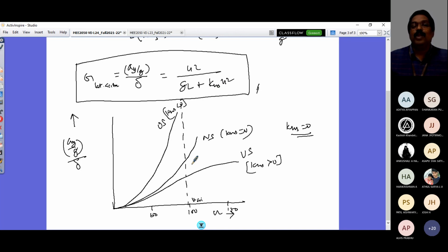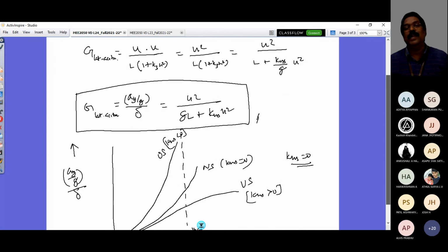So if you take those values, you can compare three vehicle segments of the same brand and do a comparative study. Such a steady state gain is quite useful, and that would help you to calculate your critical speed and so on in the functions in your code that you are writing using these equations.